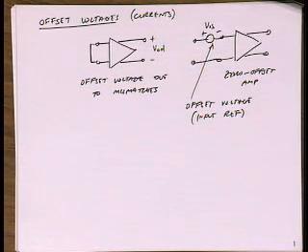I heard something. Anybody? Here's the mic. Varies with temperature? Yeah, that's right. As we'll see, this offset voltage has a temperature dependence. It's going to be some fraction of overdrive voltage, VT, kT over q, and so it will vary with temperature. We'll do a simple calculation today and see how that temperature variation is. But that's a pretty slow variation, right?